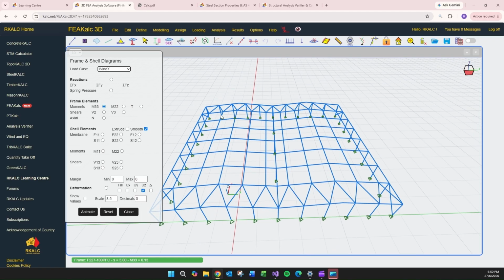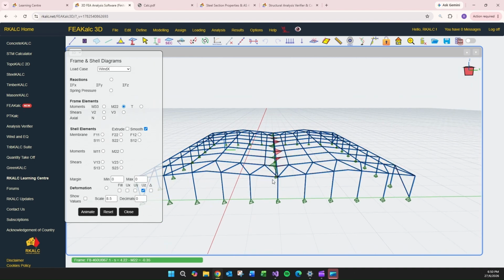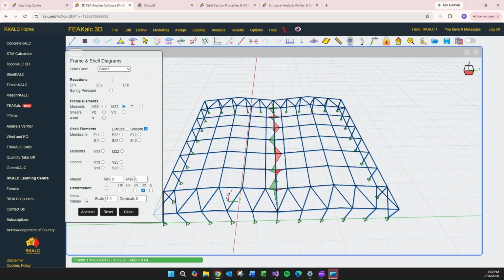When the X, you see that is X direction. It's all moments coming. Like you've got here a parabolic curve onto those columns, because we've got a line load, and everything goes down to triangulated bending moments in this direction. If you'd like to read the other bending, M22 here, you'll see that the central valley beam is subject to moments. We can look at those values separately.